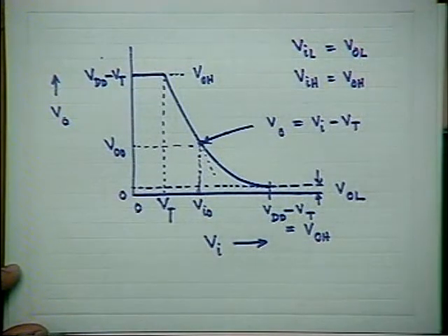And you have noted that under that condition, the gain, the transition dVo dVi, is equal to minus 2 beta R into U, U being the normalized output voltage itself.